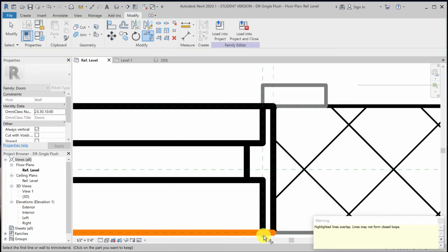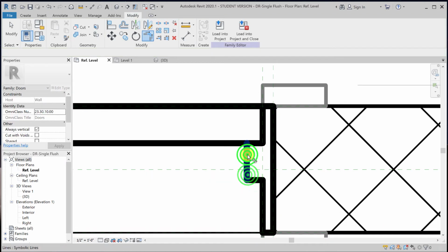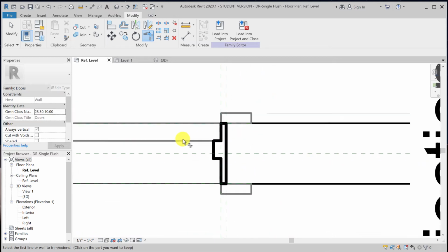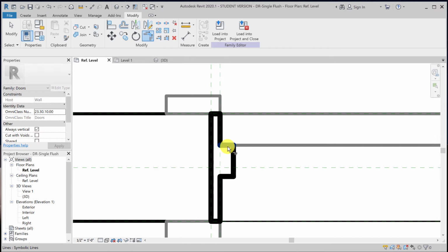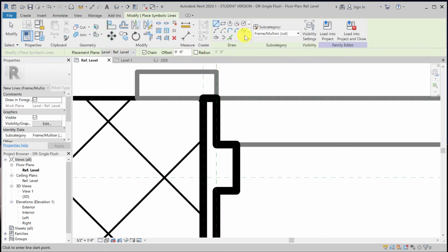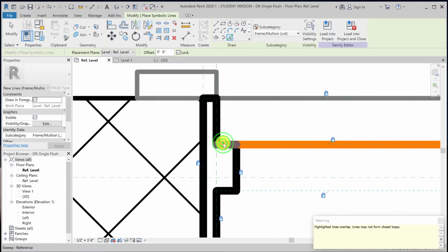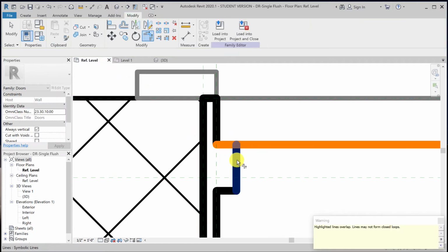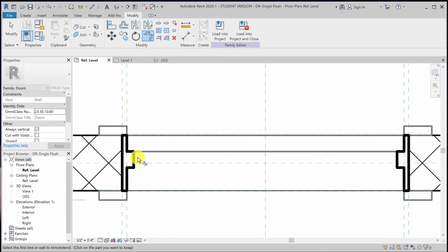Okay. TR, trim extend. So we're going to clean that. Just to make sure that I don't make that same mistake on this side because I went pretty quick there, I'm going to undo this. Okay. Annotate, symbolic line, pick. Good. I think I did. So I'm going to tab, select, make sure I select the sweep reference. Okay. And then TR to trim it. Now, technically, we pick line and we lock to the geometry. So if the geometry moves, the symbolic line should move with it.